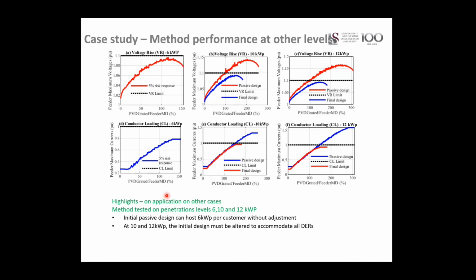Sorry, gentlemen, I think we have a slight confusion in terms, because I think Solani and Marcus are thinking of loaded in terms of consumers drawing a demand, and Lewis is talking about actual amps in the feeder. So yes, when the load is lower, it is more adverse, because otherwise some of your generated PV will be used by your loads. Yes. Did you get that, Lewis?